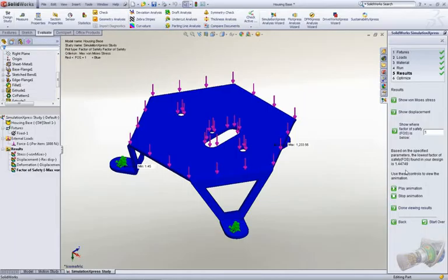This is an example of Step 8 of the engineering design process, redesign. In the first iteration, you used more material and determined that the part is very safe. In the next iteration of the design process, you removed some material to make the part lighter, cheaper, and better for the environment, while still maintaining a factor of safety above 1.